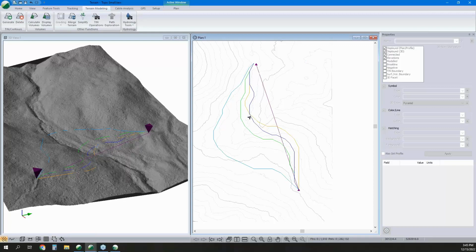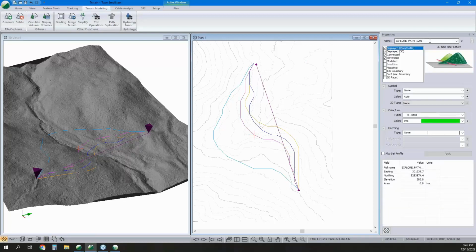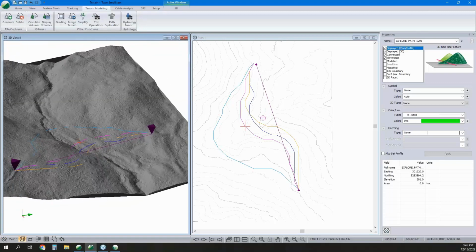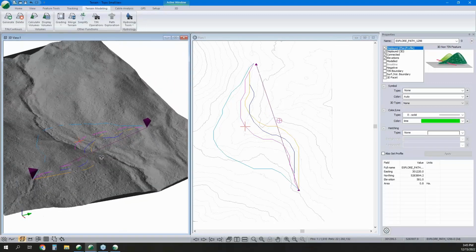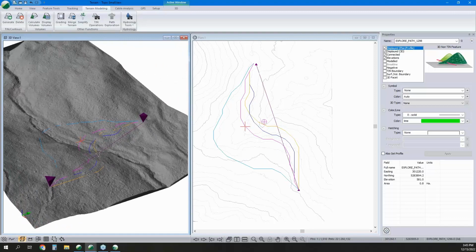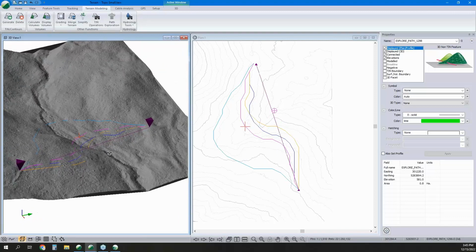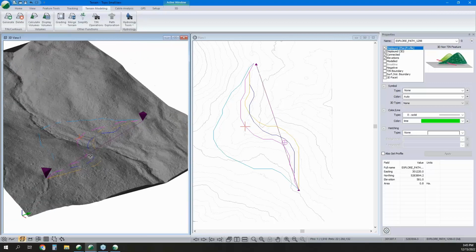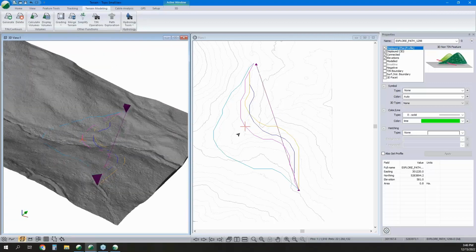And we can look at these and say, well, that's based off our cost algorithm. It's a cost of $12.98. This costs a bit more, a bit more, a bit more. So that's our optimal solution. It makes sense. We're contouring around the slope and it looks like we're crossing at a fairly good location. It's not extra long. It's not taking unnecessary amounts of fill. So yeah, just a couple clicks of the button and away we go.